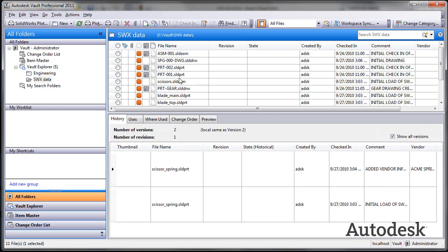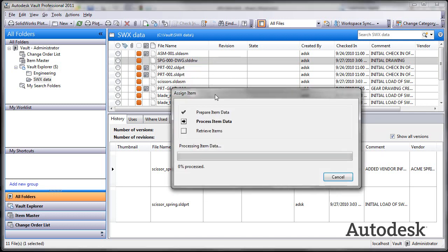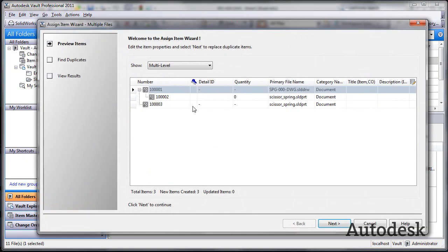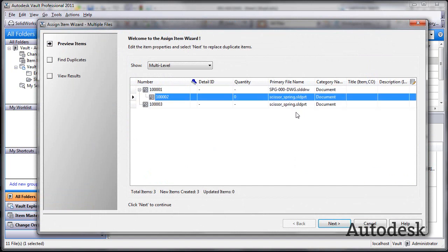That being done, we want to talk about things like bill of materials management or EBOMs. Well, we do that inside of Vault Professional with a tool called items. So we simply can assign an item. In this case, I'll do a very simple example of just that SolidWorks drawing in the part file. Now remember that part file had configurations. So here we recognize there are two parts as part of that individual part file because of configurations, but only one is actually used in this drawing.